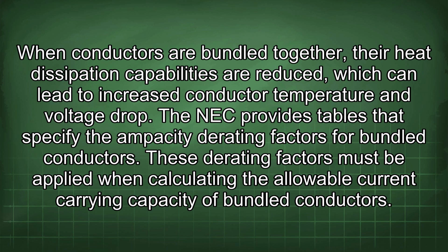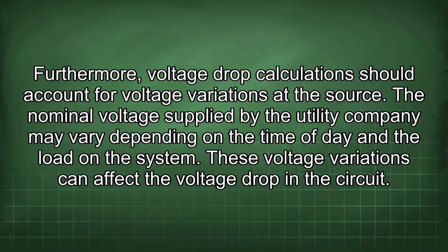The NEC provides tables that specify the ampacity derating factors for bundled conductors. These derating factors must be applied when calculating the allowable current carrying capacity of bundled conductors. Furthermore, voltage drop calculations should account for voltage variations at the source.